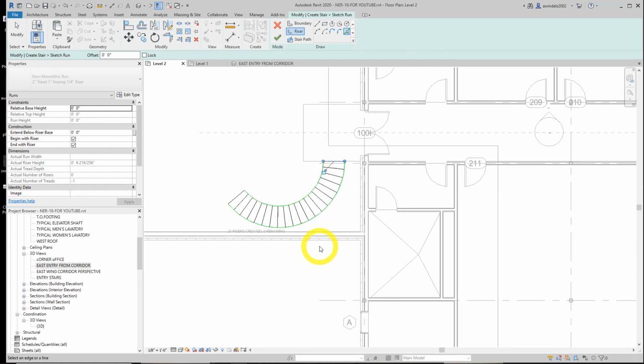Next thing, we pick the stair path button, another new thing. These are all new commands for us here. Now hit stair path. You hover in here, it'll find the center, the invisible center here. We still need to have the pick line command. I almost forgot that.